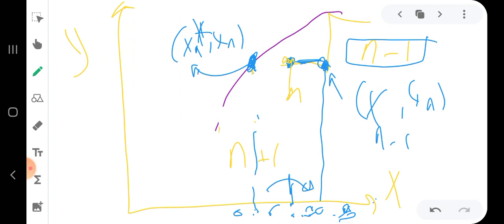Then again you draw this, and remove the extra part using the equation. Then you continue like this, and so on. So you will get another number of stages. This will be the actual number of stages using the Murphree liquid efficiency.